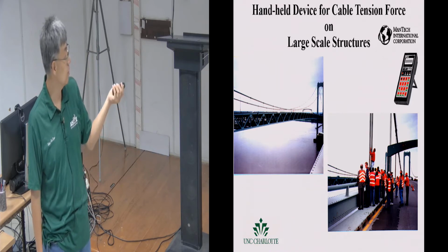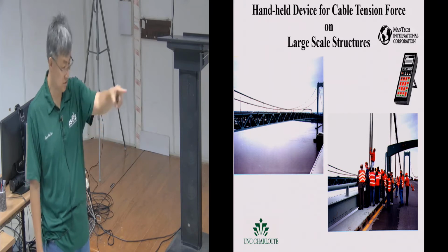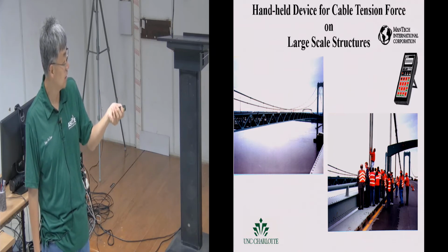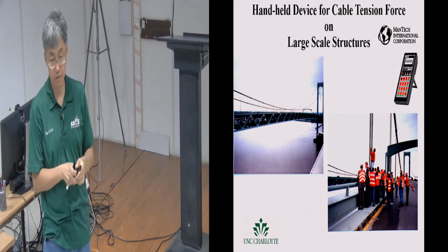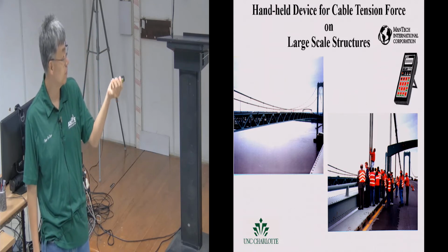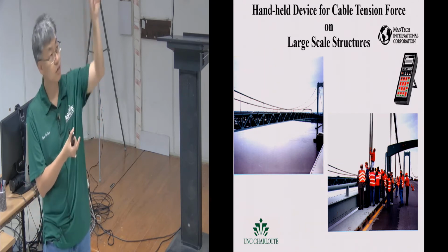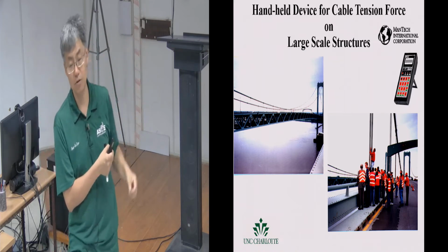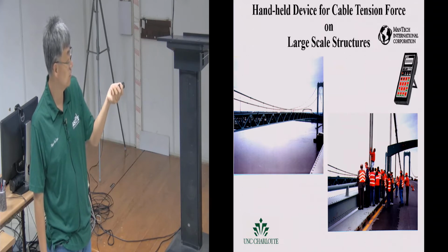This is another famous bridge, the Delaware Bridge. We did a demonstration of our device, and we invited many state DOT engineers to come and see it. In this case, the Delaware Bridge hangers have an excessive vibration problem due to the boundary conditions, and that was the drive for developing this device. We're envisioning a handheld, very light device. You can go inspect every hanger, and just go across the bridge testing. That's our motivation for developing our own device.